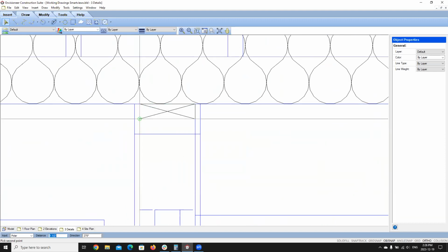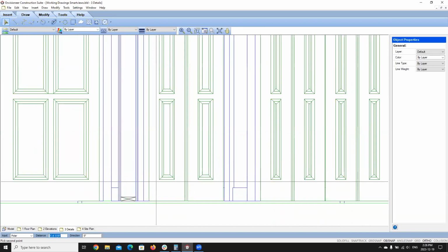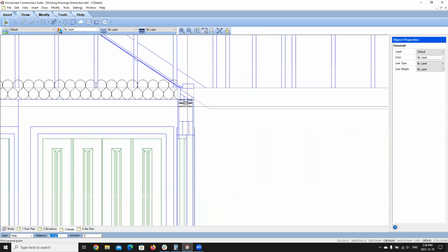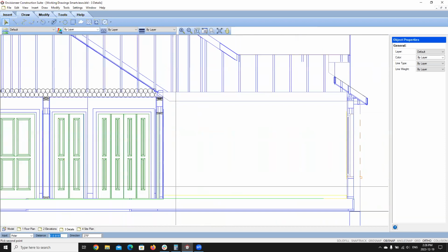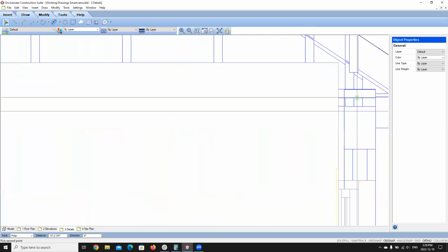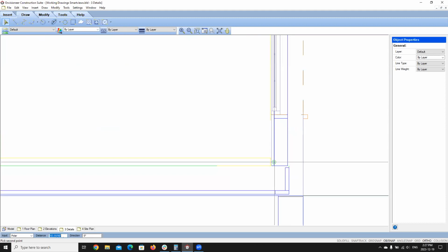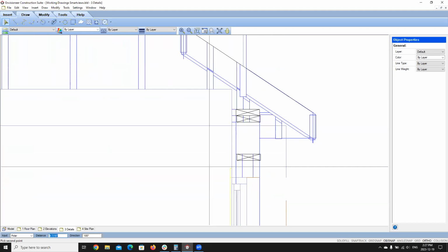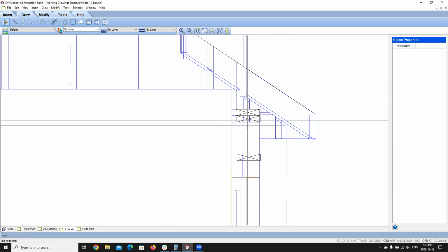And then I just very quickly add in all of my wood sections through these areas. Now, when it comes to headers, I will drop one in anyways, and then I come back afterwards and modify it, and I'll show you what I do there. So again, I'm just going to add in all of the masonry for these particular areas. And then I say finish.